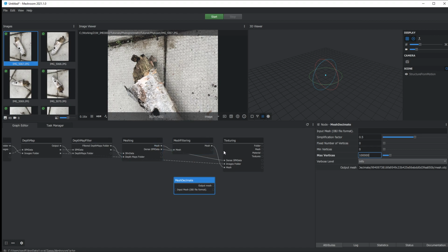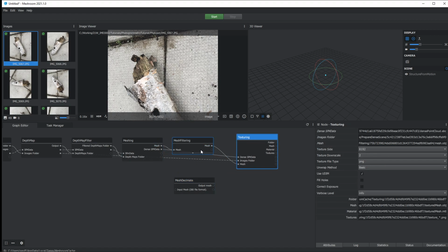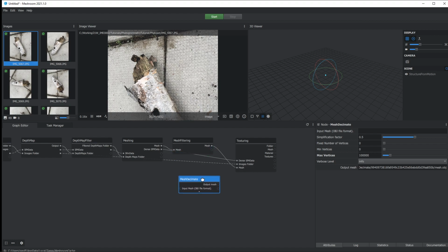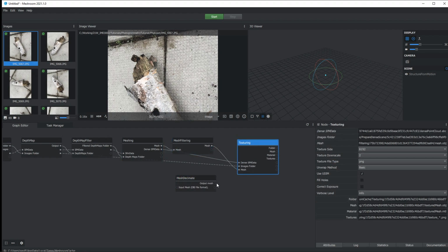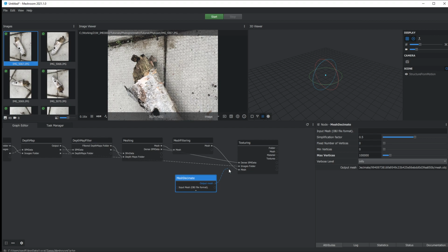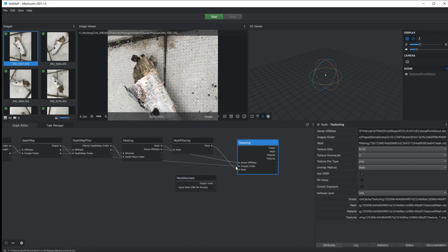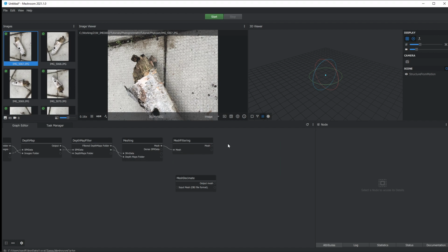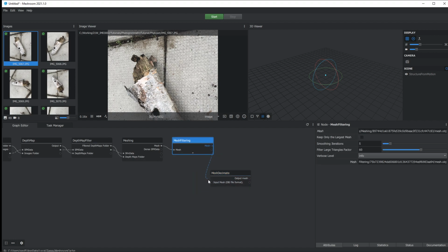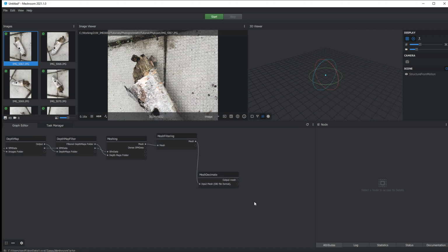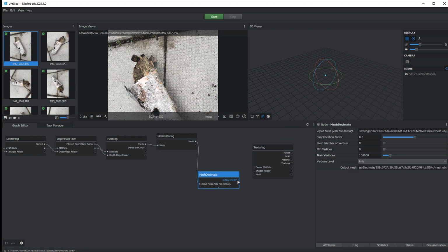And let's just connect this in so that we get this node integrated into the network here. So for some reason, we can't connect stuff to a texturing node that already has an input here. So I found, strangely enough, we have to actually delete that. See, so mesh goes in there, and then we can create another texturing node. Bring that back. Now we will be able to connect output mesh to the mesh input.